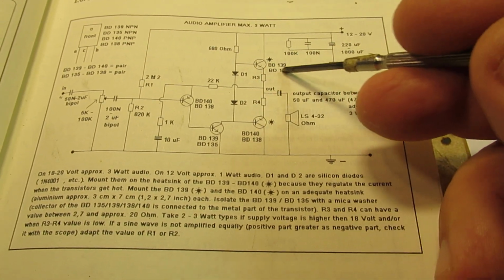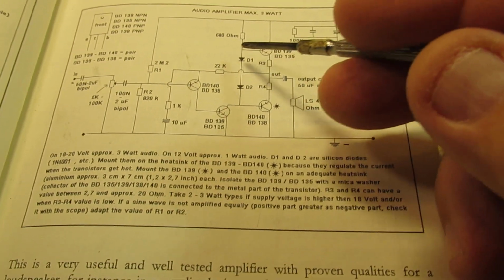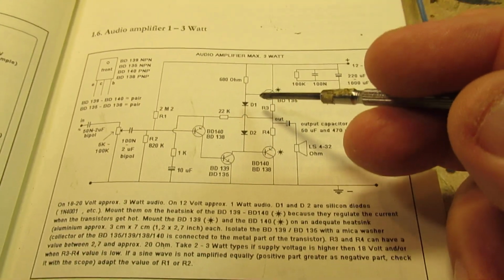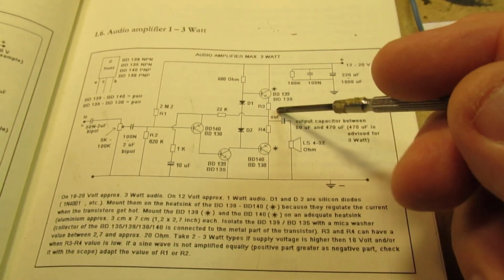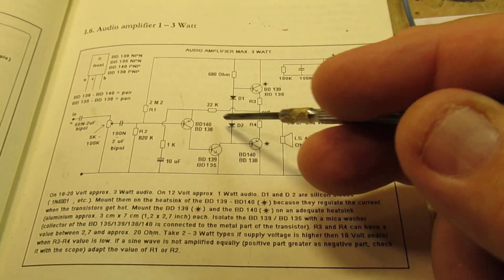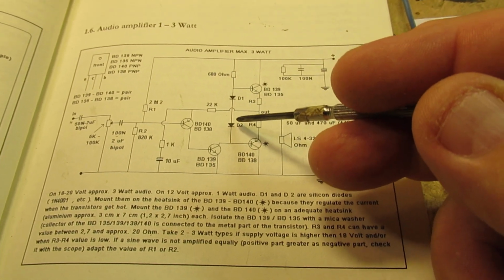But when you have a Darlington here, so another transistor that must be driven, that voltage drop must be higher. And that voltage drop is very critical, and in many schematics, in books, etc., you sometimes see a potentiometer here to set the quiescent current in some way.